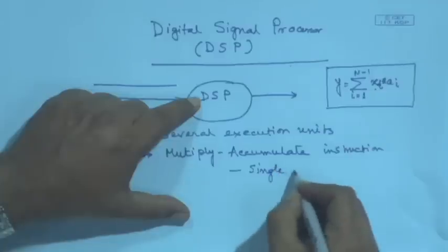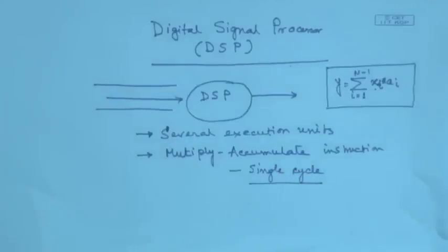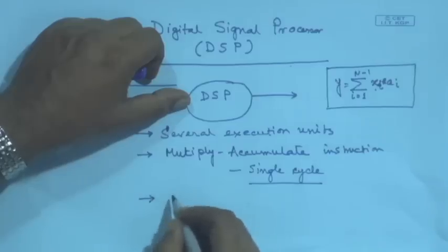Or I will have to have a very fast multiplier, which multiplies and then adds, thereby saving some time. But in a DSP, there are multiply accumulate instructions which are single instruction cycle, specially designed. And there are other instructions also besides the single cycle one. There are scopes of efficient vector operations.